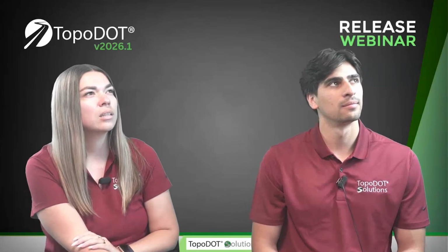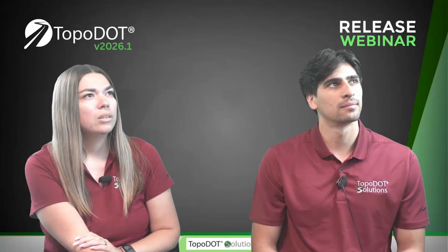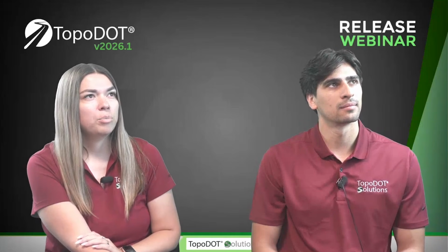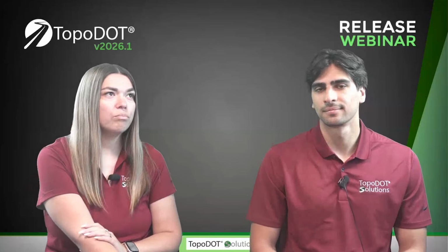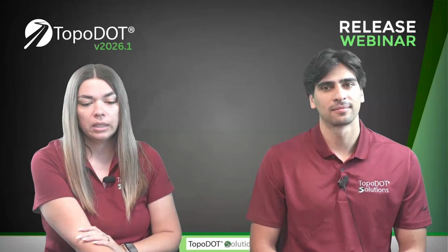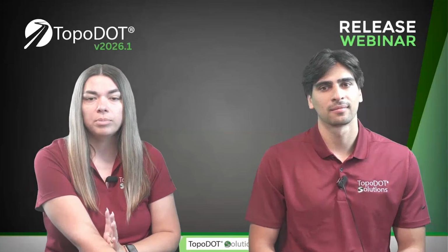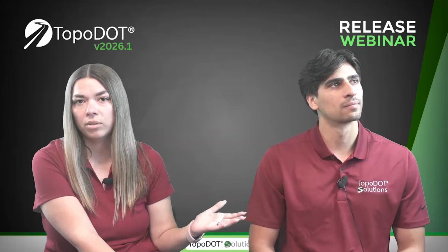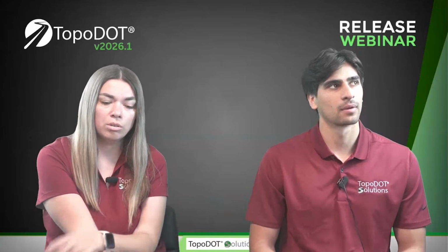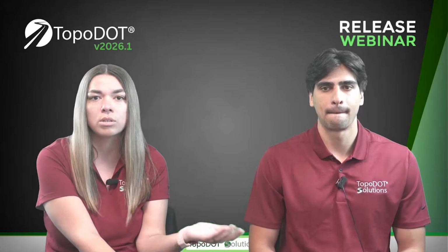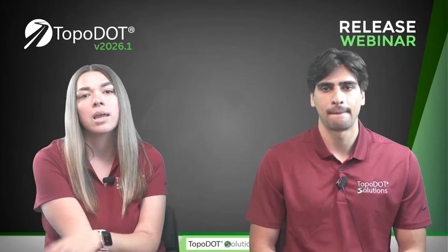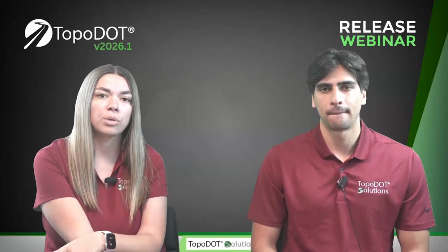John is asking, does the point cloud need to be classified before running the building outline tool? Well, technically, the data needs to be cropped. Whatever method you are using, it's up to you. You can use a combination of different cropping tools, such as cross sections or classification routines. And then the tool is just going to do its job.